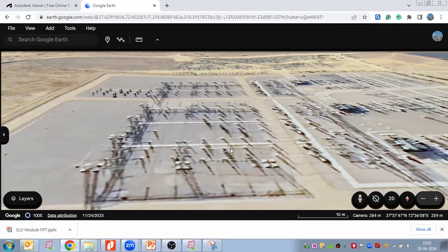So here we have the substation at the site. Now here we have the selector switch. Because suppose you do not have a selector switch and you want to take the local testing of the equipment. So how will you do the testing of the equipment? You will not go each and every time to the control building, and you are not going to operate equipment from the control room building. There should be a facility available that you can operate equipment closely, locally from the equipment level as well.